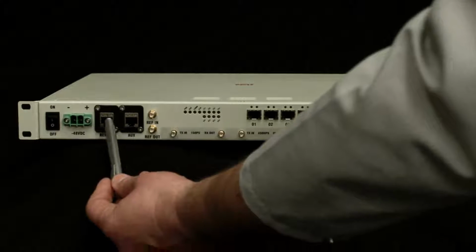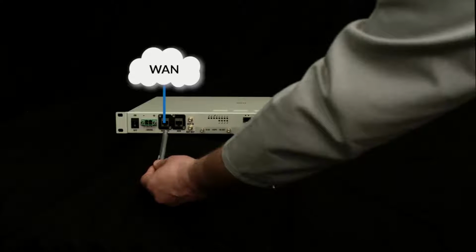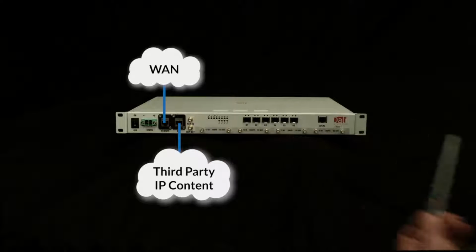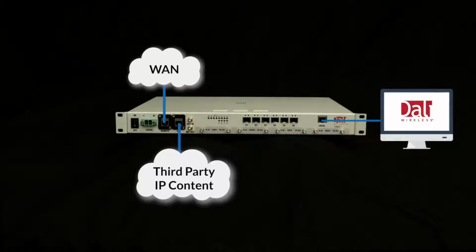The two Ethernet interfaces, the first one is to connect the unit to the wide area network. The second one is to deliver the traffic from the IP appliances connected to the remote units to the Ethernet backbone. We also have a local Ethernet port used to connect a laptop so the user can directly browse into the web server located inside the host unit and get graphical user interface pages, or GUI pages, which will enable him to control and monitor the system.